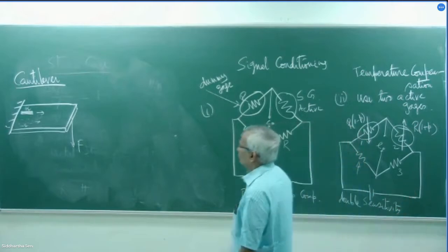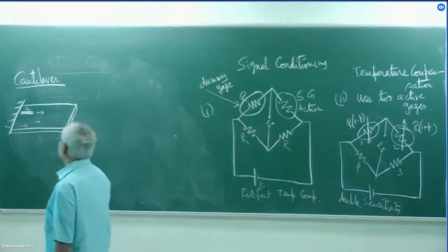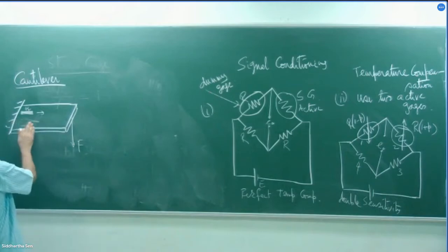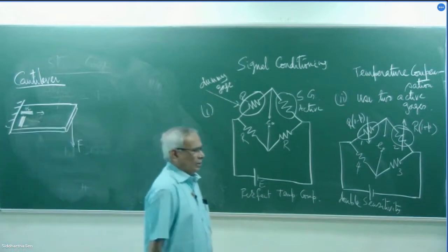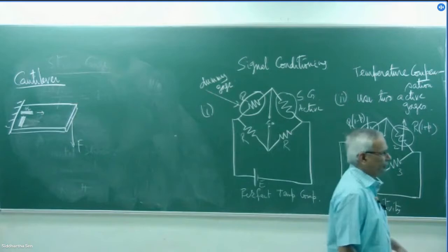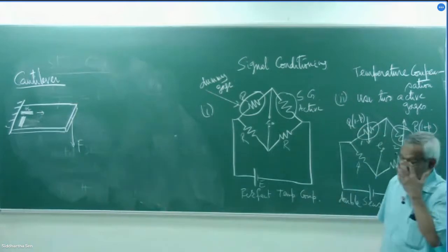Obviously, we can also do another thing. Instead of connecting at the bottom, I can put it on the top itself, but in a direction perpendicular to the first strain gauge.